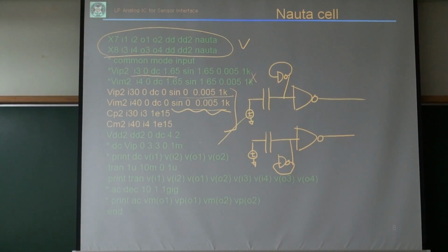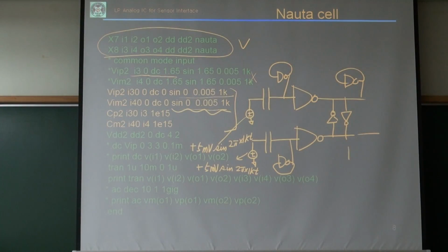This one is just a 5 millivolt sine, 2 pi 1 kHz. This is the same thing, just a common mode input, right? Common mode input. And the previous one is differential mode input, all right? Something like that.